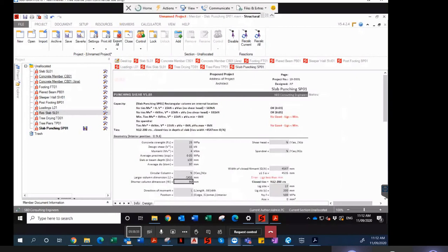It becomes an issue when the loads are quite big. So if we increase that load to say 50 kilonewton, then we are getting close. You see, even with 90 by 90 and a 50 kilonewton load, it's still not punching through. Can you see that, Ronit? Yeah.